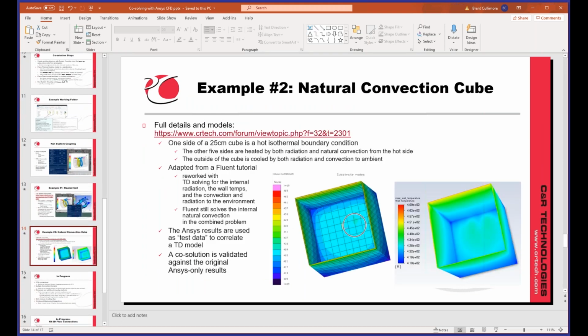This looked kind of finite difference-like, but it's not. It was a finite element model. And so, yeah, in order to provide that coupling and all the shape factors and so forth that are required for mapping, it does need to be finite element. And again, we're hoping that people start in SpaceClaim and either go into Fluent from there, or TD Direct, or both. And then that's a pretty natural connection.